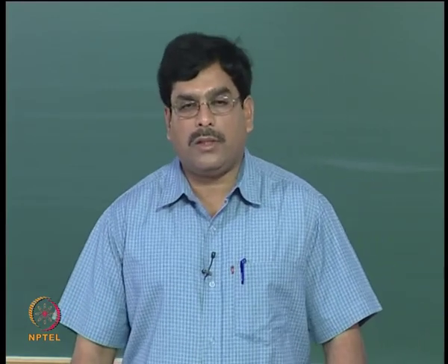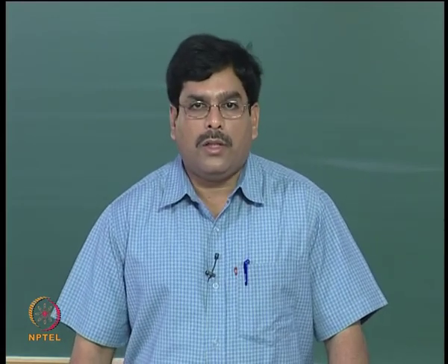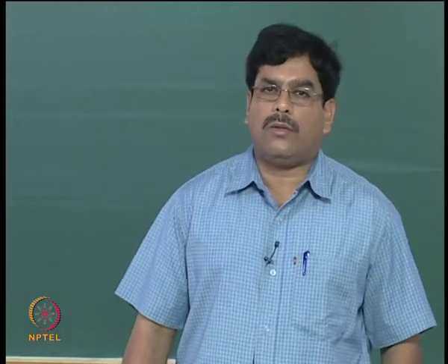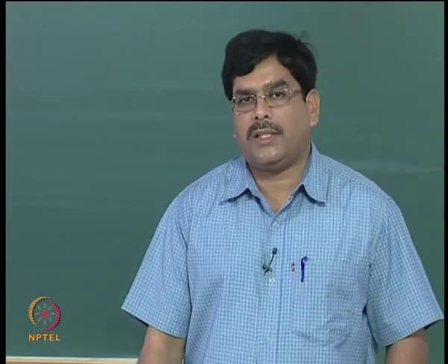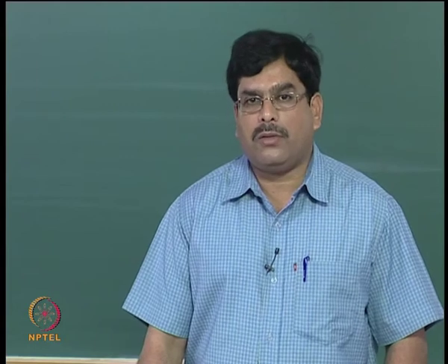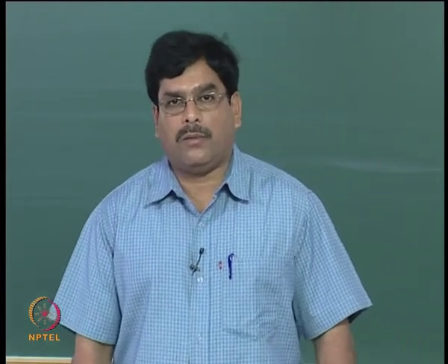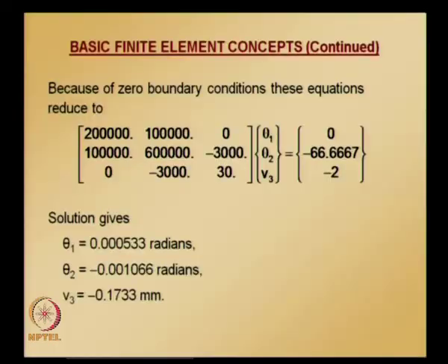Whereas in element 2 a distributed load is applied, so when calculating moment and shear in element 2 we need to apply fixed end moment and fixed end shear correction.